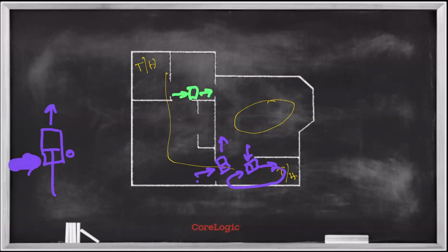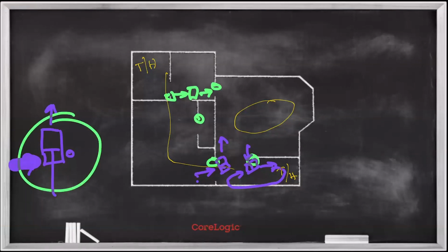So everywhere you've got these openings between two rooms, the air mover you're going to use is going to be this type, whether it's a low profile or a standard traditional carpet dryer, so that you can bend that air 90 degrees and draw it from one room and drop it into the next. The rest of the airflow you use to boost air around a room doesn't really matter what type it is. But at those openings, you've got to use an air mover that will bend that flow, and it's got to be installed in that clockwise direction to make that bend occur.